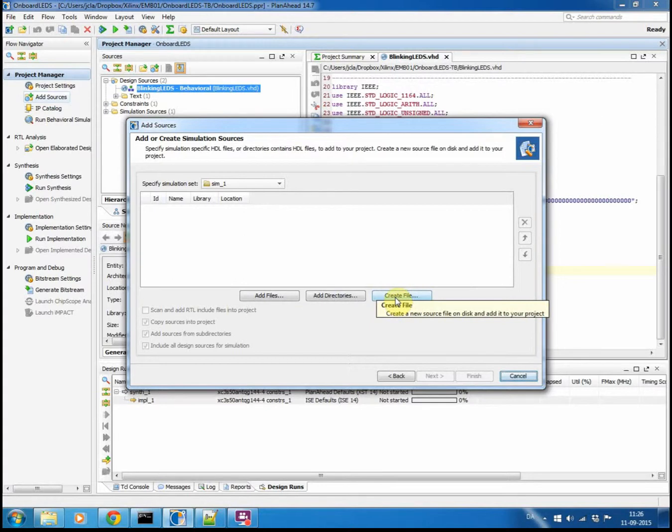What we are really creating is what we call a test bench. So we are maintaining our current implementation of our hardware, that will be the counter and everything to blink the LEDs. That is the one we want to test. That becomes the unit under test. And in order to test this unit, we need to place it in a test bench. That's the file we are creating here.